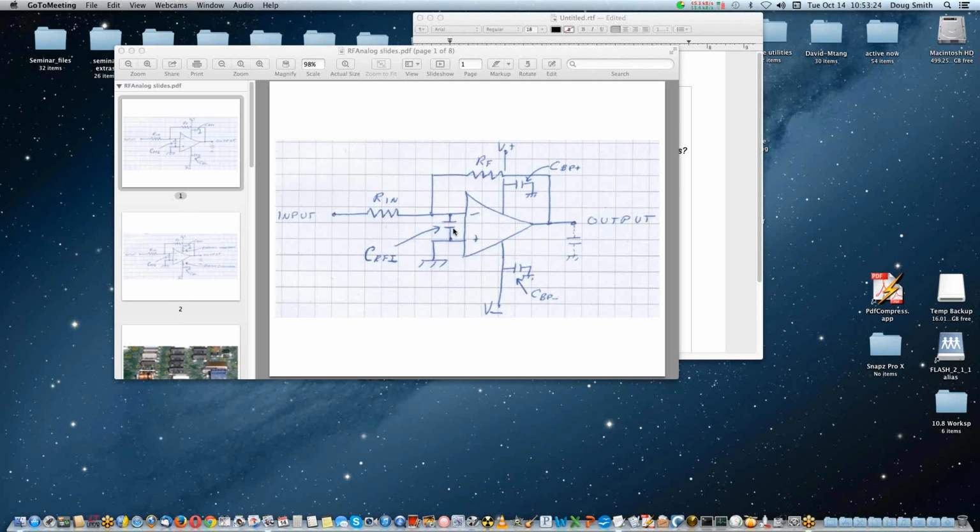Another question: many new op-amps are featuring EMI filters. Any comments on the effectiveness of op-amps with internal EMI filters? Haven't seen any of those, or at least I haven't used any. You could imagine putting that little capacitor inside, but then I'd worry about what the capacitor is made out of. If it's part of the silicon structure, it may not act so good for what we're trying to do.